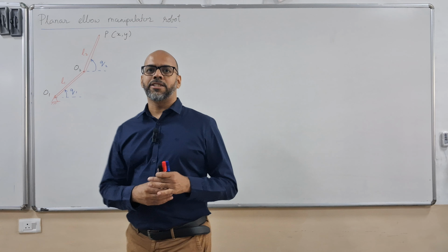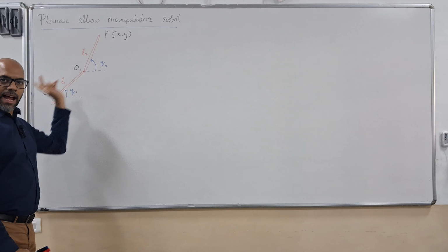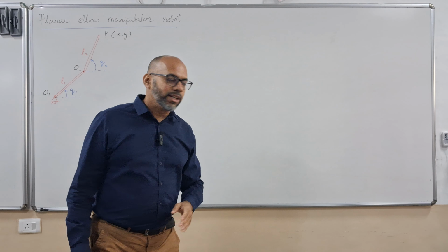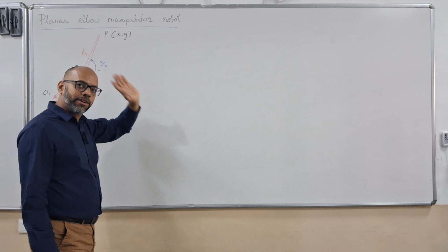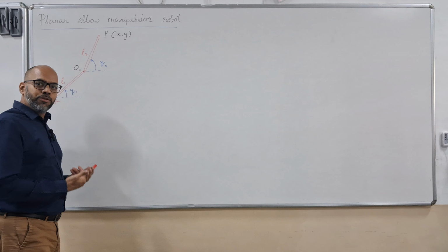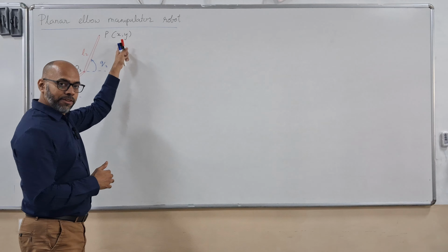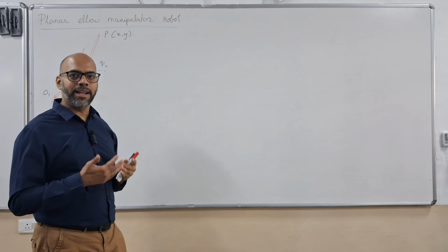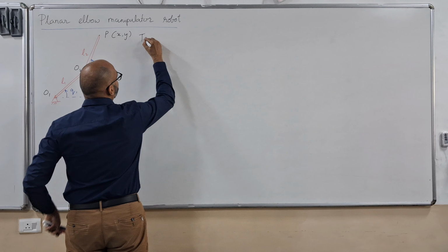In task 1 we saw, given arbitrary motions at the joints q1, q2 and q1 dot and q2 dot, how to calculate the x, y end effector coordinates and the end effector velocity components x dot and y dot. Now in task 2 we need the exact opposite of this. Given end effector positions, we want to find out what the motors need to do, what q1 and q2 should be.